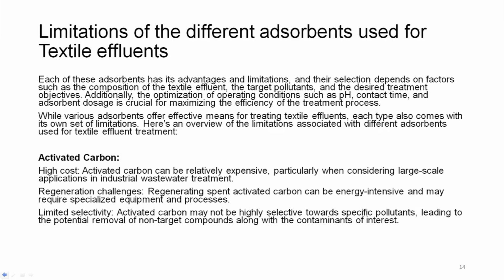Regeneration challenges. Regenerating spent activated carbon can be energy intensive and may require specialized equipment and processes. Limited selectivity. Activated carbon may not be highly selective towards specific pollutants, leading to the potential removal of non-target compounds along with the contaminants of interest.